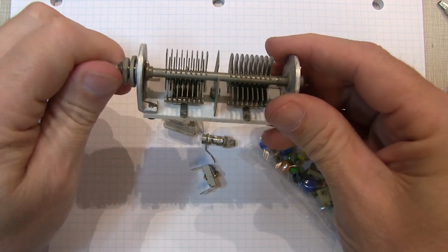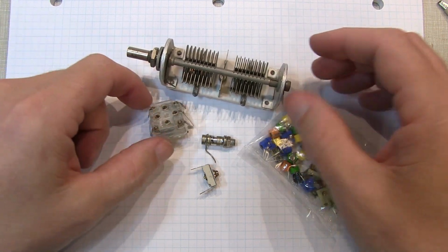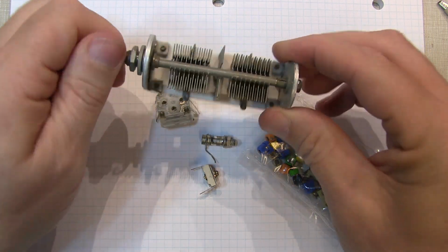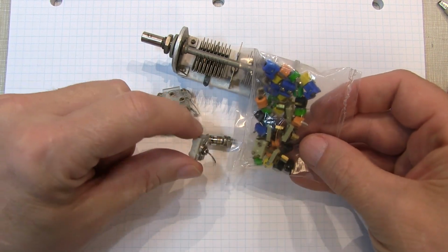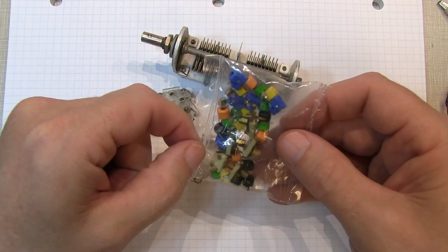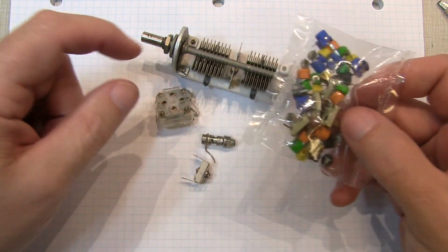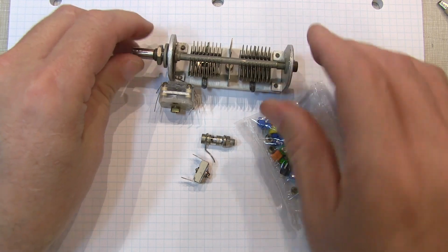But in general, all of these are typically used for RF applications, where devices like these two are designed to be kind of tuned and operated all the time, whereas the trimmers are typically set and adjusted to tune or align a circuit, and then they're left alone and never adjusted again, so they don't have the durability of some of these continuously variable devices.